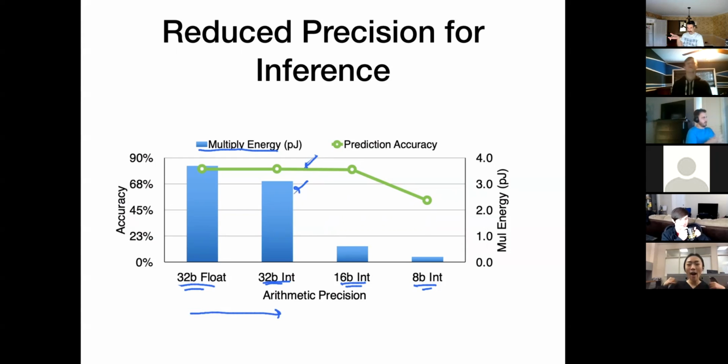This is the trade-off space, right? So with all of this precision, you get similar comparable accuracy, that is fine, but you see that with this, you get a lot better energy consumption, right? Much better than these two that you have before, especially when it comes to going from 32 to 16-bit integer representation.